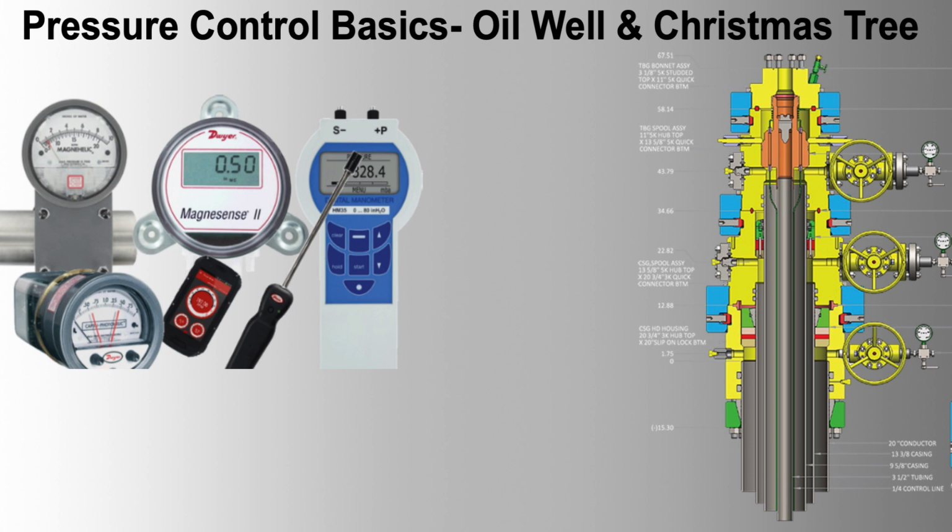3. Installation considerations. Location. Proper placement is critical to avoid vibrations, extreme temperatures, and ensure accessibility for maintenance. Mounting. Choose suitable mounting methods, e.g. direct mount, remote mount, based on the well's layout and environmental conditions. Protection. Use protective housings or enclosures to shield instruments from physical damage and harsh environmental conditions.